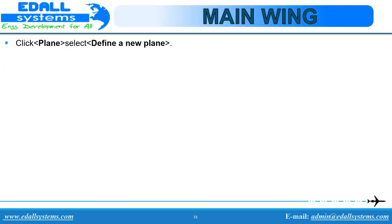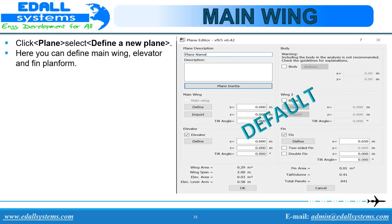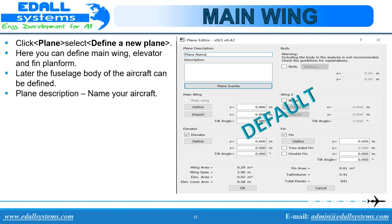Click on Plane, select Define a new plane. We have the plane editor screen opening. This is a default window. Now we can define the main wing, elevator and the fin here. But to define the main wing, let us first deselect the elevator and the fin. Now we have the plane description here, where we have to enter the name of your aircraft.